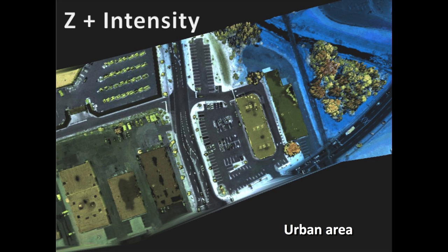Now this is a LiDAR image. Color variation, again, is the elevation. So the blues represent this floodplain here. The red represents these building groups. But then the brightness represents things like street markings, the road center lines, parking bays, moisture on the roof of these buildings, and things like that. None of these things would come out in the coordinate information alone, but they come out in the intensity information. So when you put these two streams of information together, you get very, very rich information content.